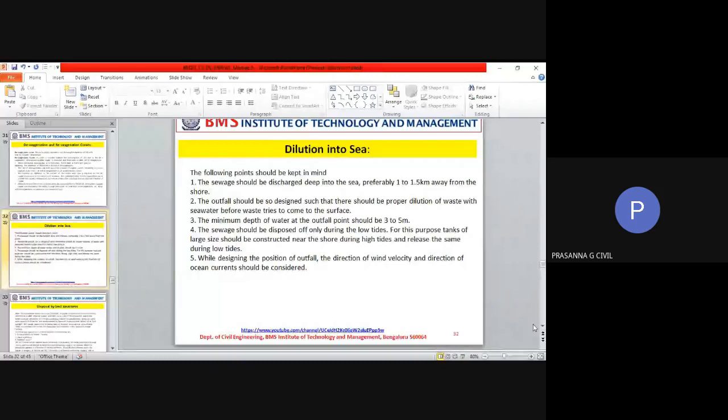Okay, then I told you to keep in mind certain values of DO at certain temperatures. Can you tell me? These are important questions for your multiple choice exams. Understood? So tell me. At 0 degree, saturation is 14.63 milligram per liter. And at 30 degree, saturation is 7.63 milligram per liter, ma'am. Okay, very good. At least that you remembered. I'm happy. You can mute yourself.